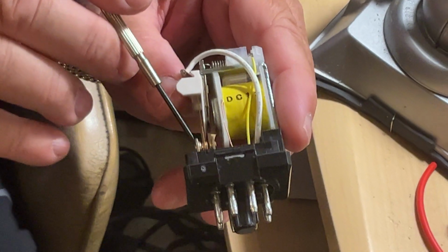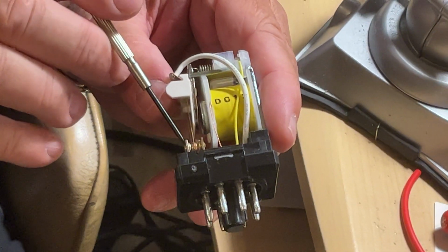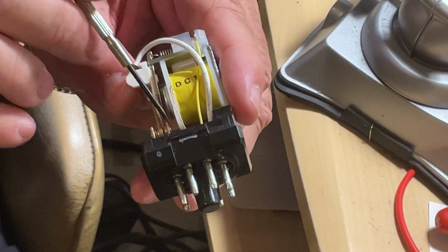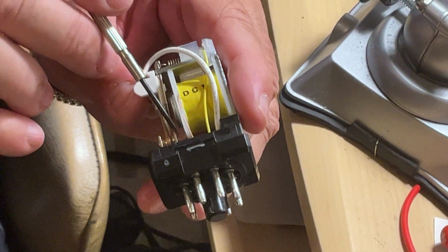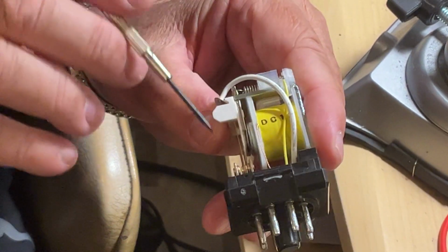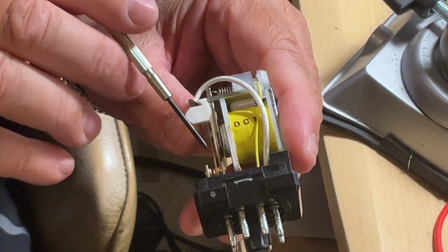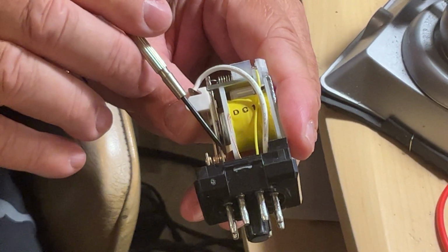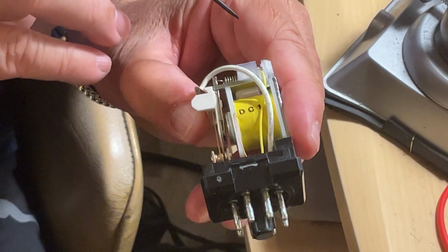This one is called normally closed, because normally when you don't energize the coil, it is closed. The other one is an open circuit, called a normally open contact. And when the plate in the middle, the pole, is moving, the normally closed contact is opening and the normally open contact is closing. That's how the relay is operating.